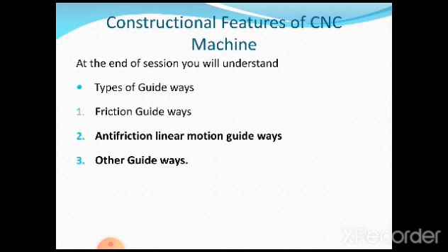In that we have discussed at length the friction guideways. And what are the different types of friction guideways, like V, flat, dovetail type, cylindrical guideways, etc. in the previous session, and their importance, their significance, and which is the most commonly used type of friction guideways. Along with that, we have also understood how best we can use the friction guideways with the special coating of material called PTFE, which we have already discussed in the previous session.